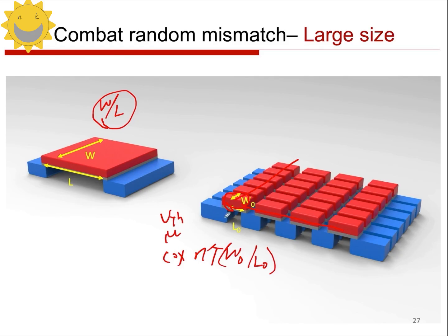But when combined, the total parameters of these transistors, after being connected in series and parallel, effectively create an averaging effect across the entire range, including the width to length ratio, which is also an average result. This means that it will add up the W0 and L0, and after the addition, it will result in this W/L.